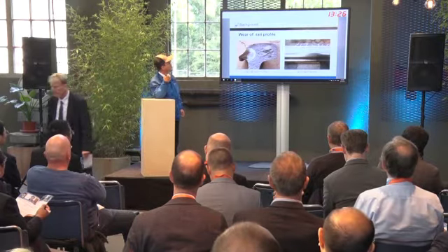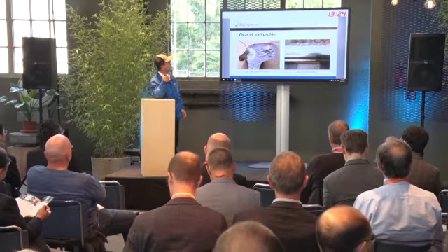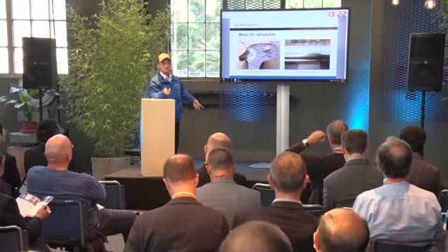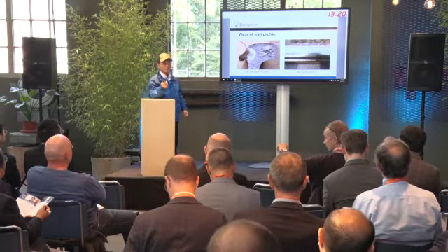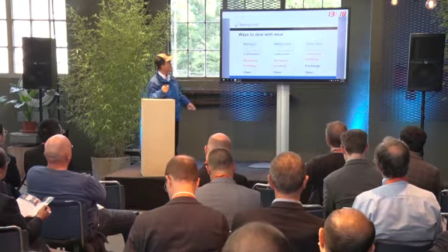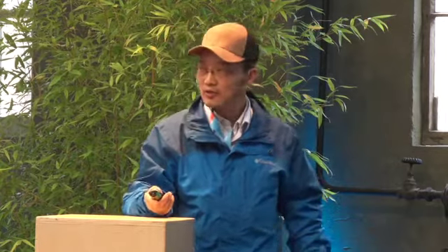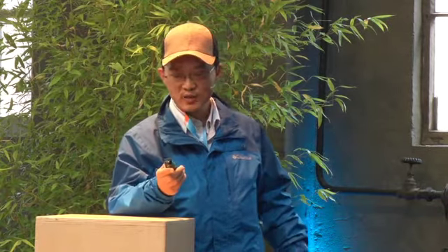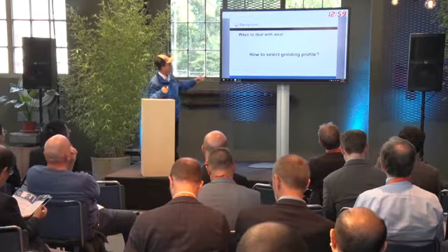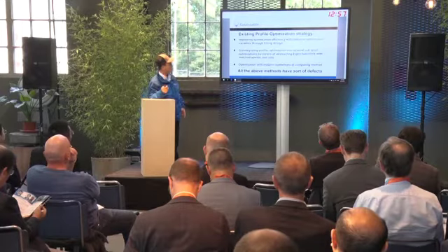Okay. Now in this slide, we can see the wear of the profiles is very serious. So we use grinding to recover the worn profiles. There are several categories; here I didn't spend time on that. And then, with the ways to deal with the wear, how to select the grinding profile.